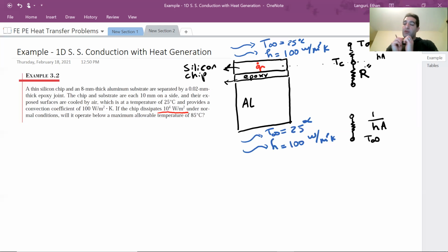Still, you have some resistance between the two substrates because of that third material. Hence, we are defining an R double prime contact resistance, which we're going to use a table to find. That's just additional resistance because in reality you cannot have 100% contact between any two substrates. I'm going to talk more about R double prime.